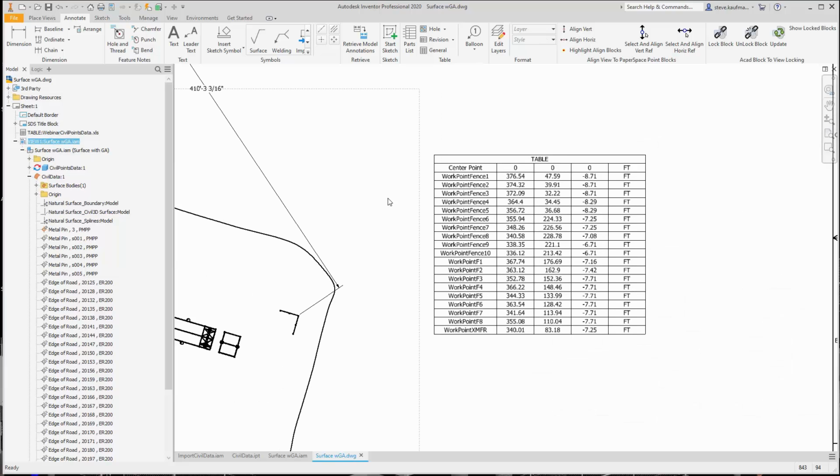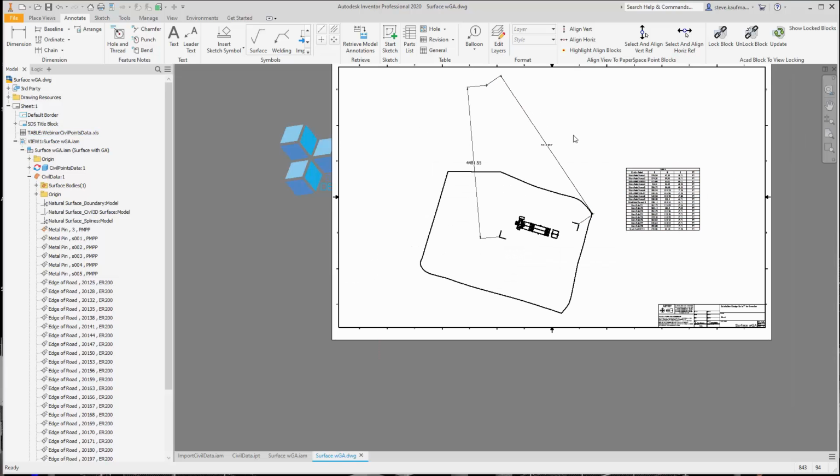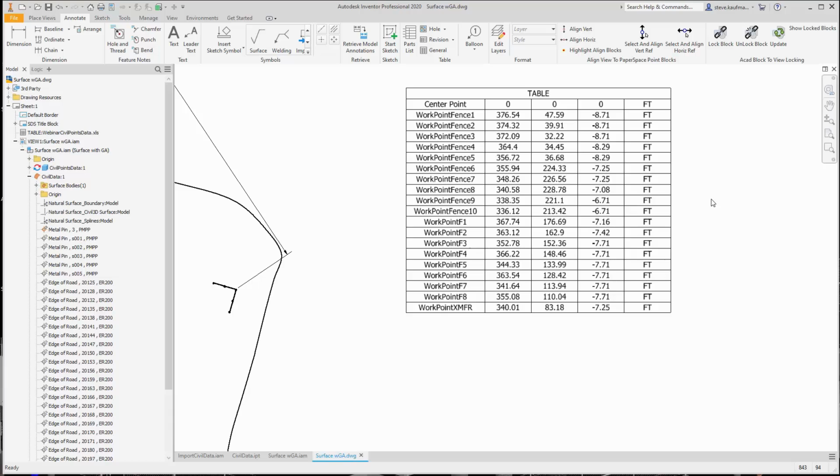So that's all referenced to 0, 0, which in turn is referenced to the geo-reference point that we got from our civil people. You can see the height change in elevation, which is the third unit here. And this table can be cleaned up, possibly have headers in it and whatever setup you want to do. But we have that information now available, and it's all referenced. All those points are referenced to that point, and we have the elevations to the top of the concrete.